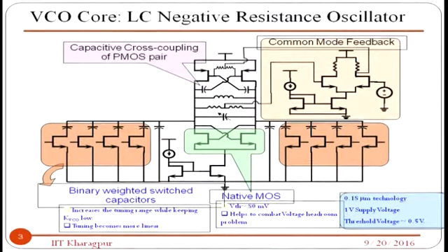So, if one of these voltages is going up by any chance, then you should have a reason to reduce it down. Look here. Suppose the voltage here is going higher because of asymmetric conditions. Then the output voltage will be high. If it is high, then this transistor, which is a P type, will see the positive voltage go up, so the current will go down and the voltage here will go up. This is how the voltage here is going up and this will go down.